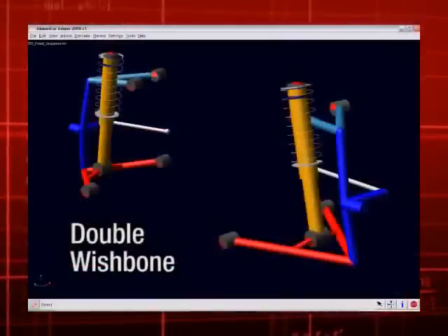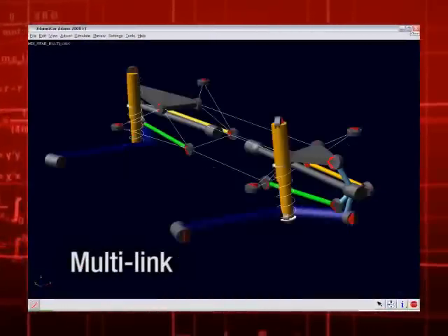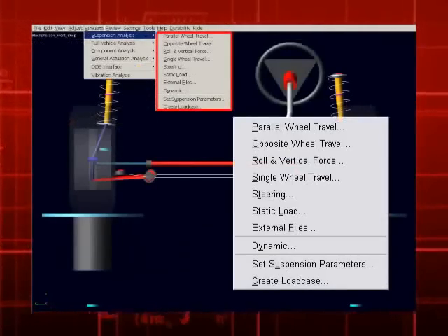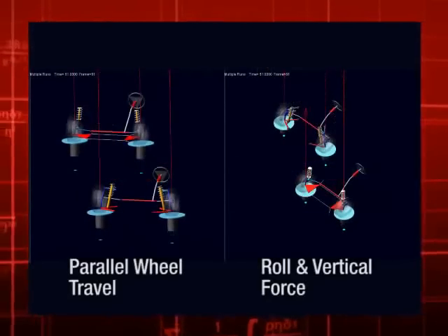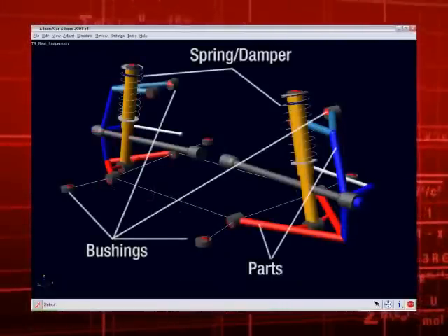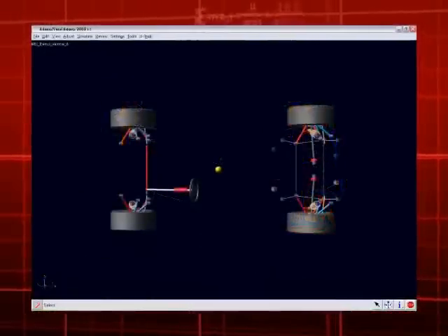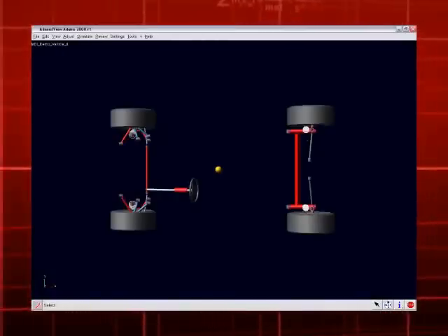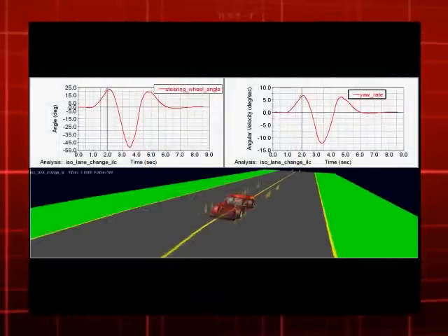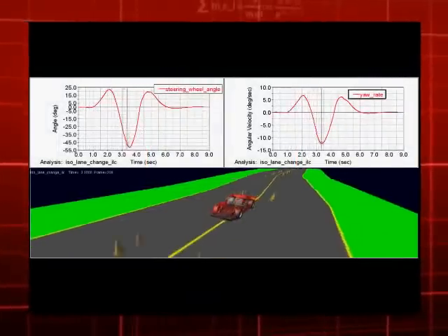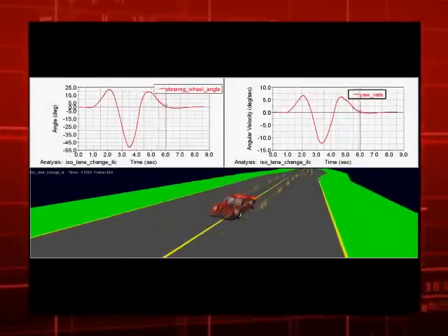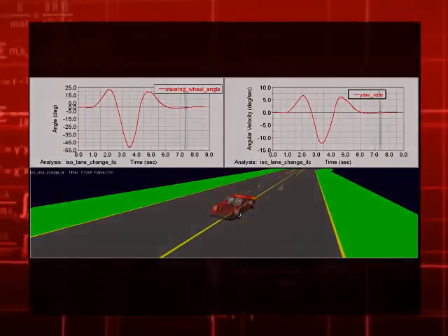Adams car has templates which capture generic configurations typically used in automotive suspensions, as well as test methods and procedures exercised on physical prototypes. Adams car separates data and form. Thus the same template and the different components, i.e. data, can be effectively used across different vehicle programs. Adams car also outputs appropriate vehicle metrics in line with standard automotive testing processes. It thus eases exchange of data amongst different departments and helps in sharing of common data, properties, and results.